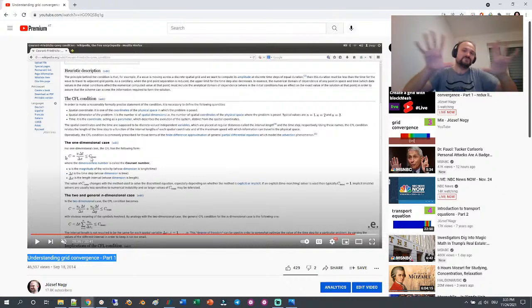And you most probably know about the Courant number. The Courant number is a dimensionless number, a numeric one, which then reduces or controls the time step size. So the Courant number is defined as the velocity times delta t divided by delta x. And usually this value should not exceed 1. In some cases you can, but usually this should be less than 1.